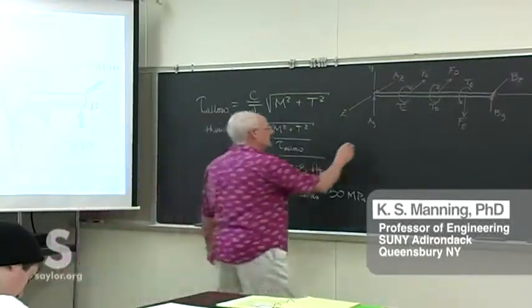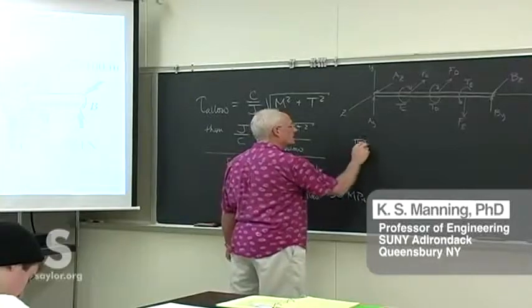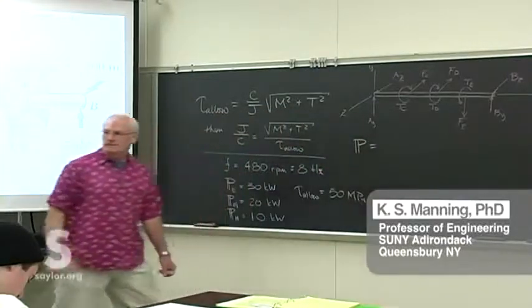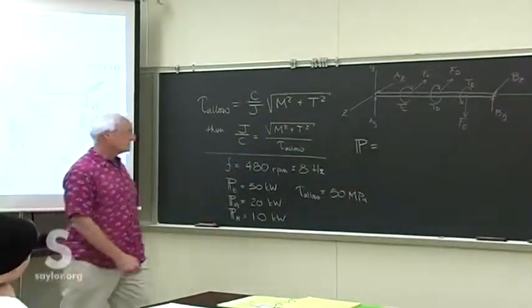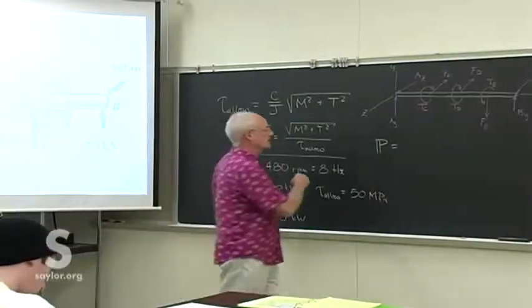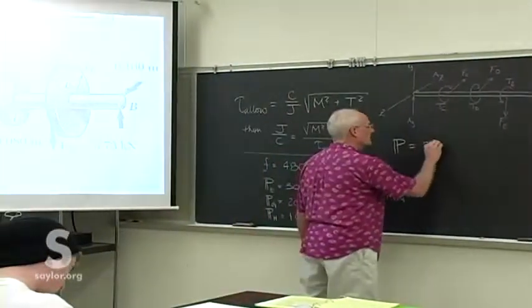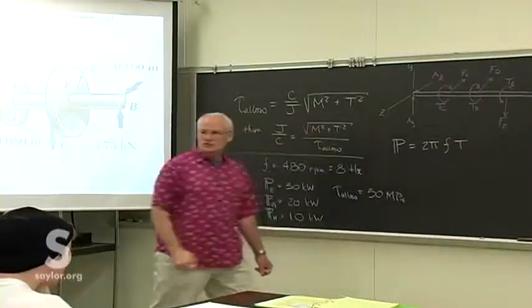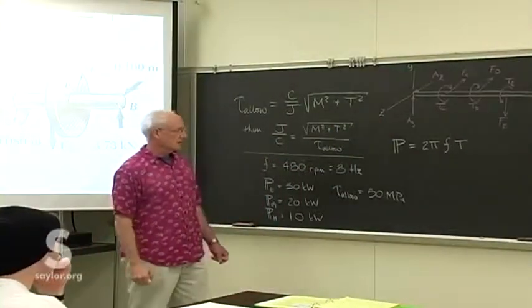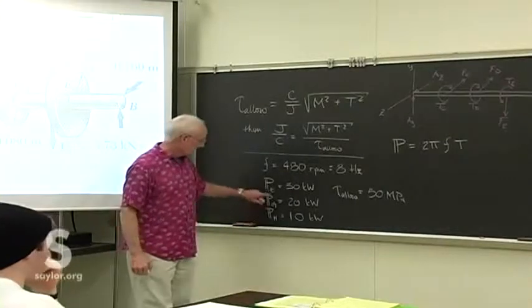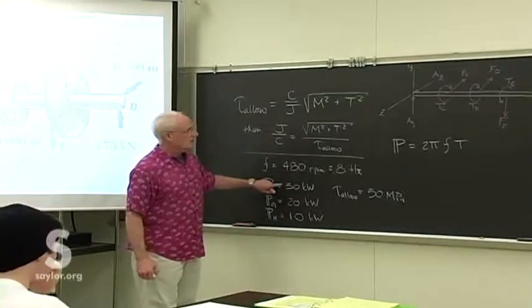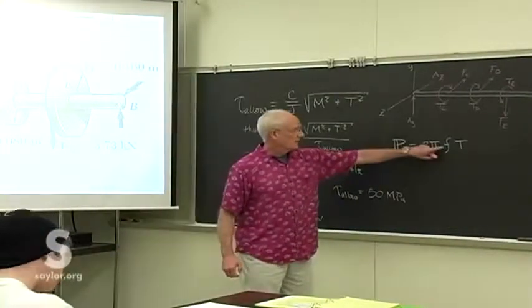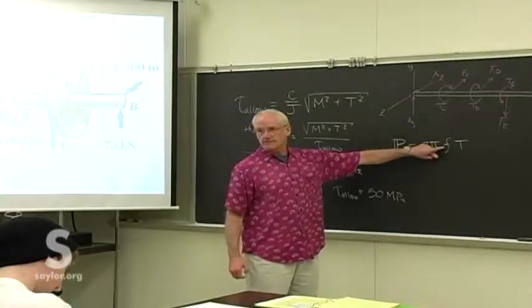And then, if you remember when we were doing these types of transmission shafts earlier, when we were just looking at the pure torsion, we can relate the power to the frequency and use that to find the torsion in each one of the places. So we know at E there's 30 kilowatts coming in. We know the rotational frequency of the shaft.